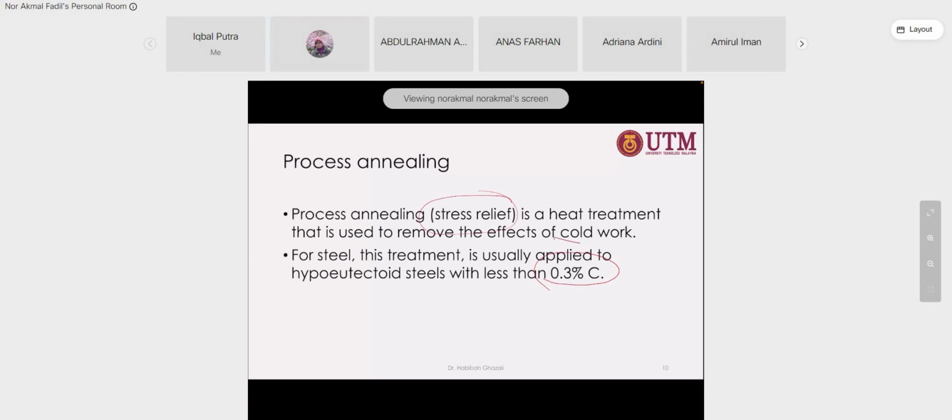During the cold working process, despite the distorted microstructure and the residual stress in the materials, the cold working effects will increase the strength by the grain distortion as well as the increment in the residual stress.